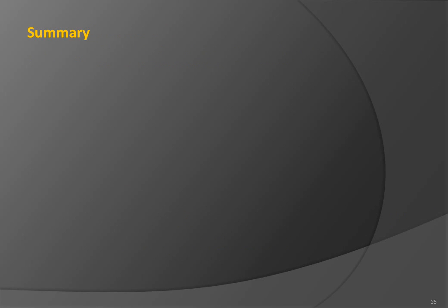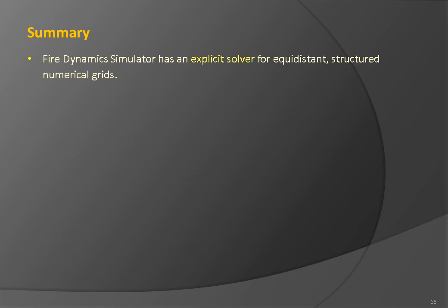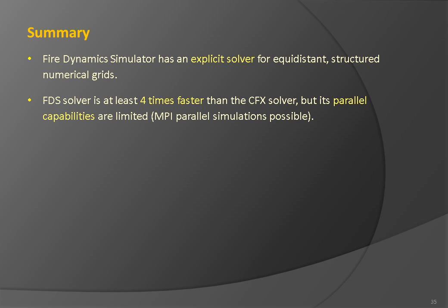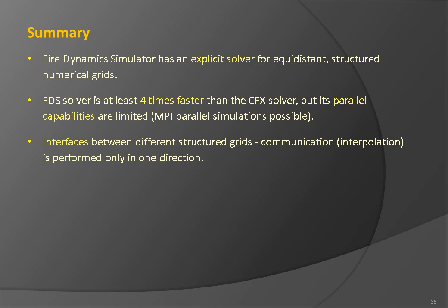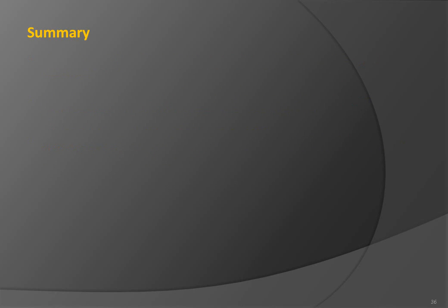We can approach quality control of simulation analyses through validation and verification cases. These have to be geometrically simple. We do not want to spend too much time preparing the cases. They have to contain the representative and predominant physics. If the phenomenon cannot be isolated to the satisfactory degree, its main parameters will be hard to establish and measure. We need to have available